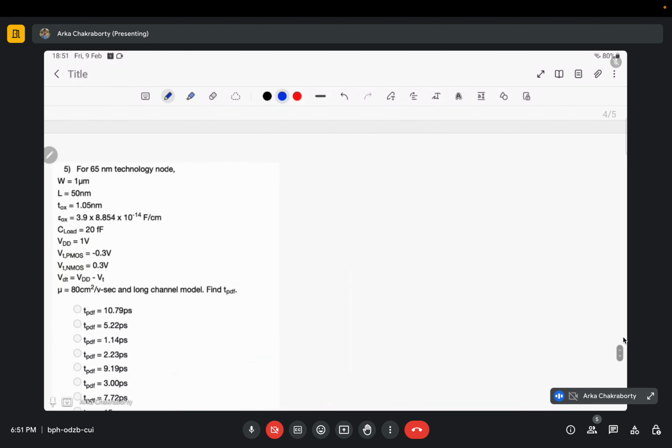Okay, so it is given that for a 65 nanometer technology node, the width is given as 1 micrometer, length is given as 50 nanometer, oxide thickness is given as 1.5 nanometer, epsilon ox, C load, VDD, threshold voltage of PMOS, threshold voltage of NMOS, VDD expression, and its mobility is given. And it is said, the most important thing, it's a long channel model, and they have asked us to find the propagation delay for falling edge.